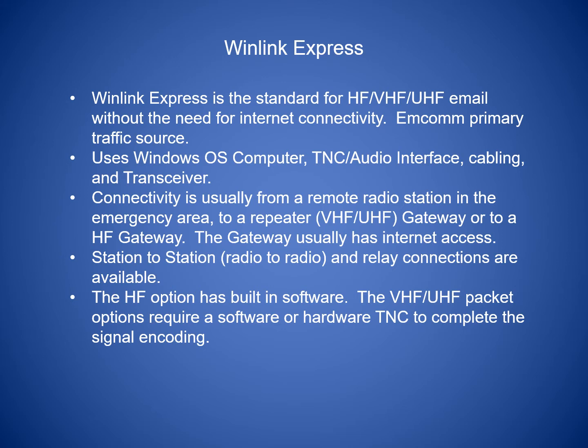It can also be connected via HF gateway, and the HF stations are also connected to the internet. The gateway usually has internet access somewhere outside of the emergency area. Station to station or peer-to-peer communications, relay connections are also available. The HF option in WinLink has built-in software. The UHF, VHF packet options require a software or hardware TNC interface to complete the signal encoding.